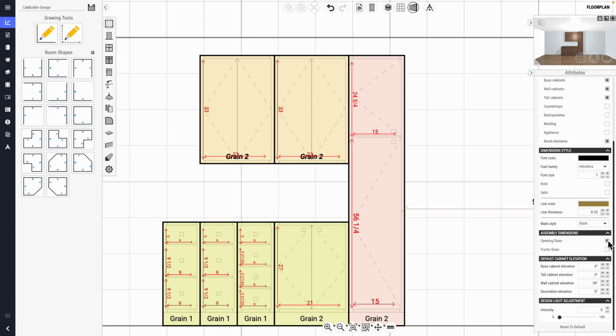And this acts in different ways for frameless and framed cabinets. Now, right now, I am within a frame construction. And what it does is it gives me the sizes of the openings from frame part to frame part. So for instance, if we look at this utility cabinet, the distance between the top rail and the mid rail, the inside space, is 24 3/4. And from style to style, it's 15 inches. And same for the bottom opening here, I have 15 inches wide, 56 1/4 tall between the bottom rail and the mid rail, the inside dimension.